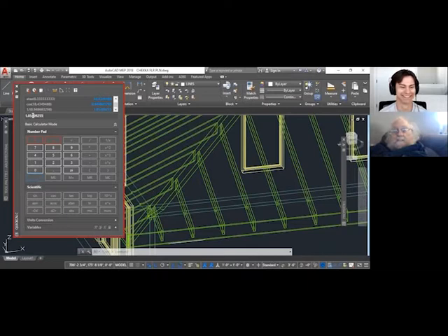Now, it's not because I'm a genius. I've worked with these numbers so much that I don't need a calculator to come up with that number. 1.054 is as etched in my brain as 1.4142 is, just because I've done this for so many years. I don't have to reach for a calculator to come up with the secant of a 4/12 pitch. But if I multiply that secant by the horizontal run of the first jack rafter, bingo, I'll have the long point measurement.